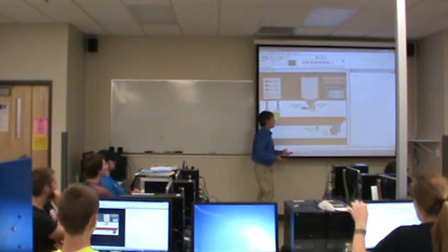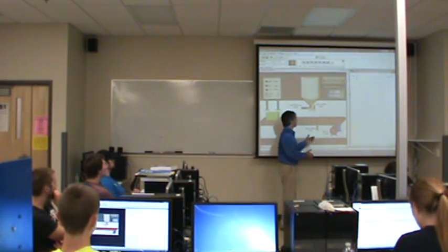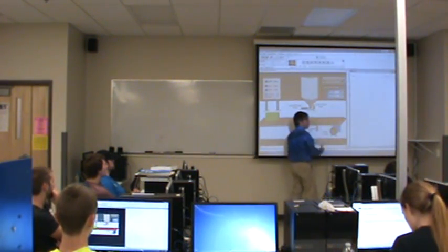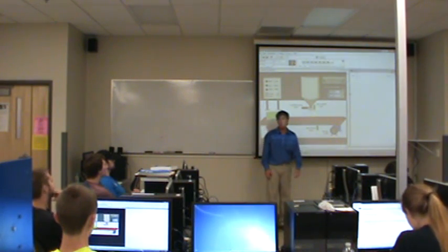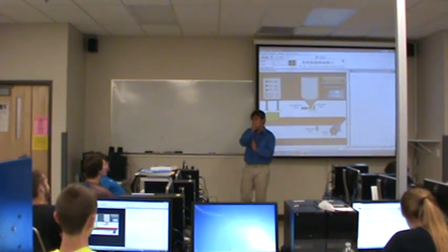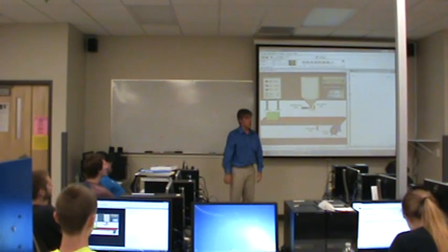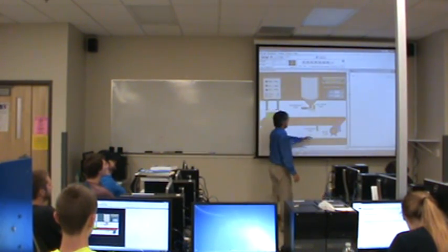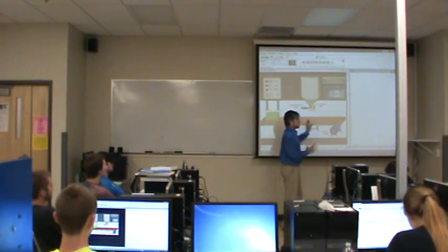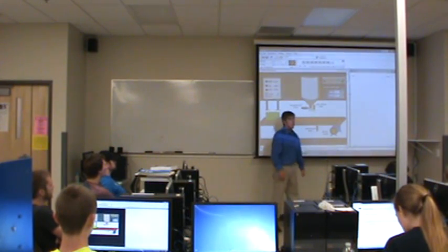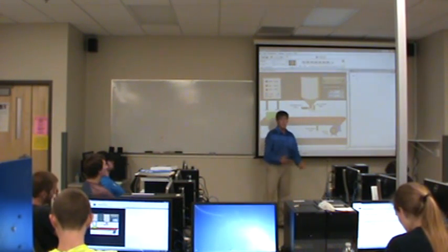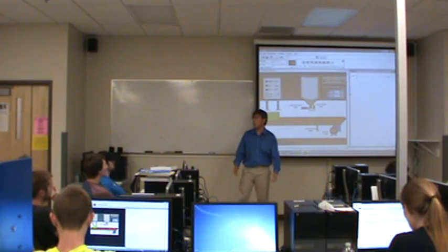box. Now, of course, you might say, well, you can solve the problem mechanically because you should move the level sensor over a little bit. Okay, that may be true. Maybe it's true that you should align those two a little bit better. You could say, well, how about if we use a timer so that after the level sensor goes off for a certain amount of time, well, then we're not going to turn on the cylinder valve, we're just going to keep the motor on. Well, that's what I would call a dirty program.